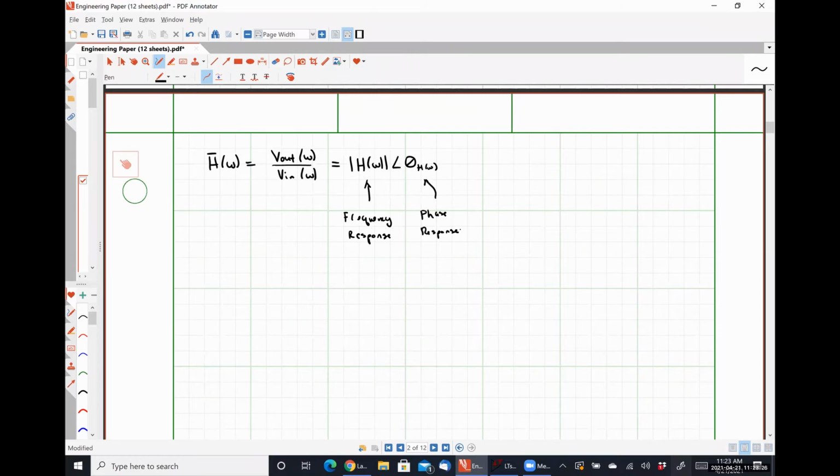And when we simulate these guys on LTspice and things like that, if you simulate a simple low pass filter circuit, or any filter circuit, you're actually going to see two lines. One, the solid line is the frequency response, and the dashed line is the phase response. So when I ask you to simulate things, it's perfectly acceptable that you're going to get two lines on your graph. You're supposed to, okay? All right, so